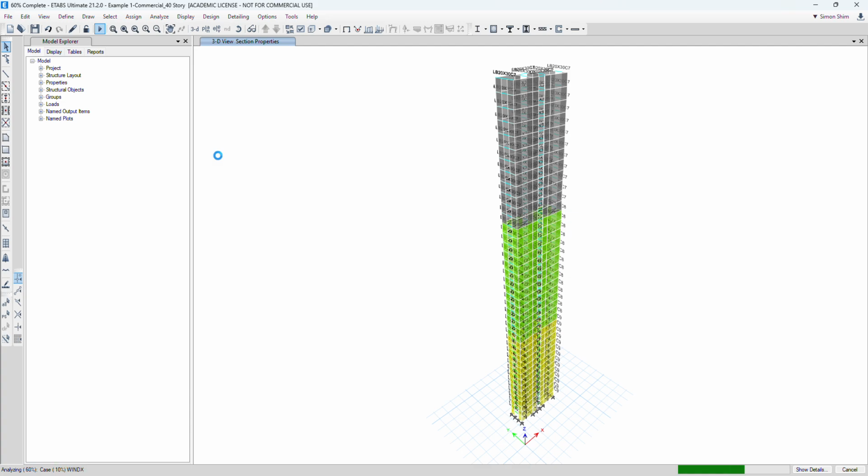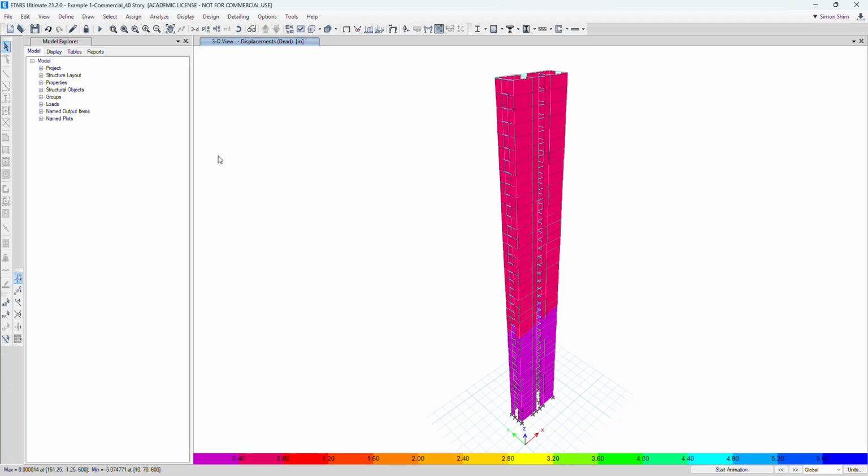So when you assign that wall thickness and the link beam thickness, you can run the model and see. You're gonna pull out the deflection diagram and dump it to Excel, same thing. So we're gonna continuously look at this, monitor how much this building deflection is improving.